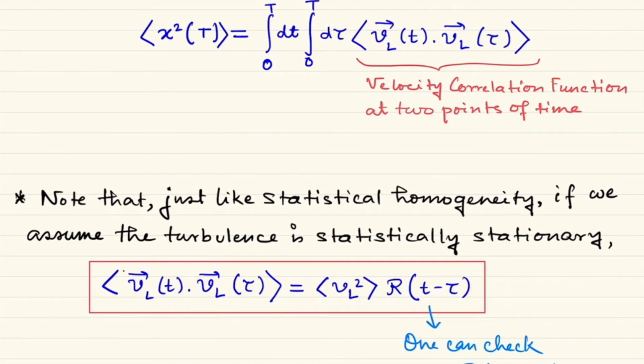Now one thing here I would like to say is that we are talking about stationarity because this is something very important for our case. And remember, in the previous discussion I mentioned that Kolmogorov, in the year 1941, obtained his famous exact relation, which was relating the third order structure functions, or the third order moments of the 2-point increments, along with the length scales.